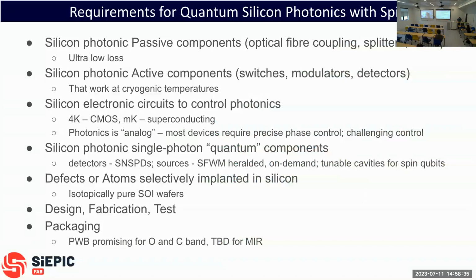Okay, so conclusions. I want to basically present to you a vision for the challenges for the field, for job security for the next 20 years. One big one that's pretty universal for anybody that works on photonics is ultra low loss components. This was important for data communications, but for quantum systems where you really can't lose the photons, basically every component that we make can be engineered better and better. So we've gone from beam splitters that have a 0.3 dB insertion loss to 0.03, maybe 0.01. So we're pushing those numbers down quite further.